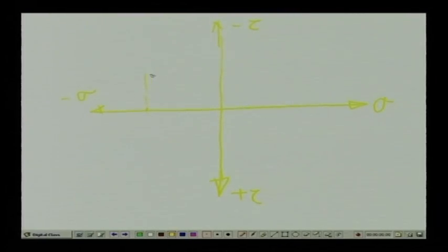So, we get the point somewhere here, which is sigma x as minus 30 and tau as minus 20. Then we have the perpendicular plane, which is the y plane, which is 90 degrees with reference to the physical plane. Here in the Mohr's plane, that will be 180 degrees, and we have positive sigma y, which is 10 MPa, and we have positive tau, which is 20 MPa.